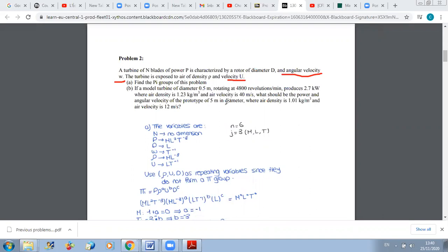In general mu should be included, that's right. But for this particular application they know that mu is not important. This is why they didn't tell you to include mu. But in general, if they don't give you the variables and you have a flow field, put rho, U, and mu.